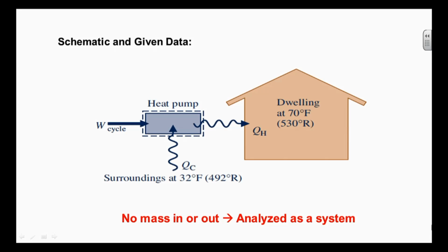Having recognized this important fact, let's select our system boundary. Remember that a closed system does not allow any mass in and out through the boundary. The only transfers allowed through the boundary are heat and work. Here it is selected to enclose the entire heat pump system as delineated on the schematic with the red dashed line. It clearly ties in the information provided to the information requested in terms of energy transfers.